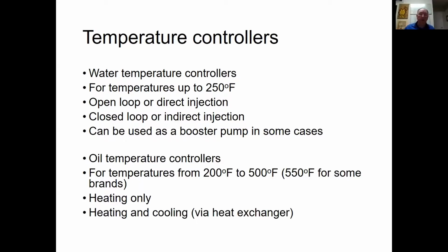If you need cooling, we have to have the heat exchanger because we can't mix oil and water, so to speak. And it's very important to make sure that heat exchanger is sized properly for the heat transfer. There are standard heat exchangers supplied with the typical basic standard hot oil units, but it's really important to make sure that heat exchanger is sized properly, because your flow rate or your heat input into the process might be 12 kW or a 1 horse application, but your delta T's might be higher, and that standard heat exchanger might not be big enough. So it's important to make sure that the heat exchanger is sized properly.